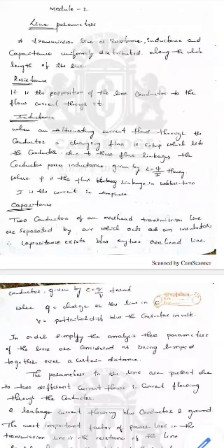If it is divided into, say, 10 different parts, for each part we calculate the resistance. When we get the values of resistance, capacitance and inductance for all the distances and club them together, we get the total resistance, capacitance and inductance of the whole transmission line. This is how transmission lines are analyzed for the line parameters, and that is the meaning of lumping.